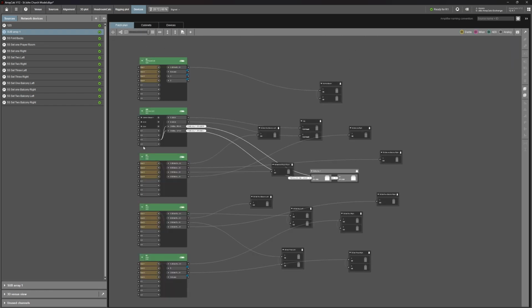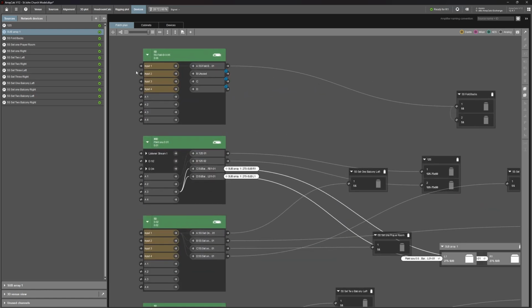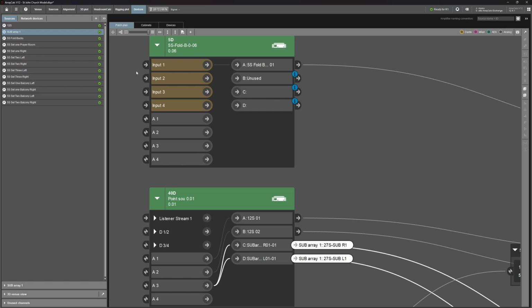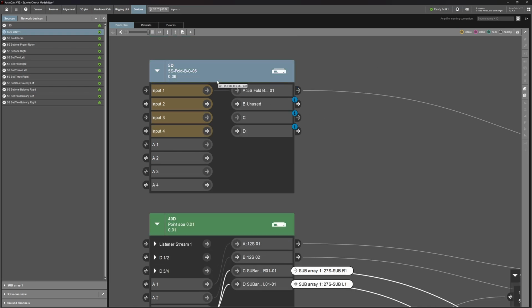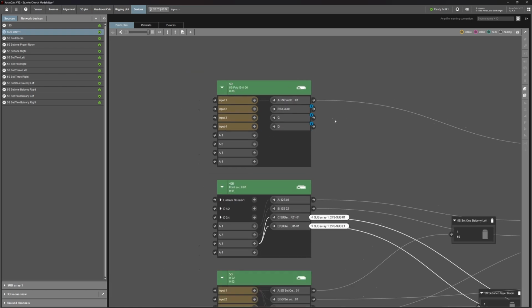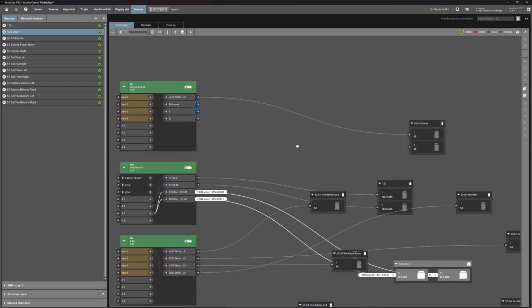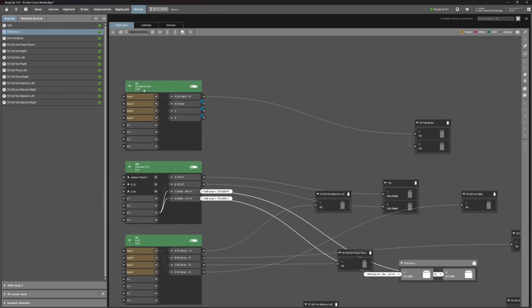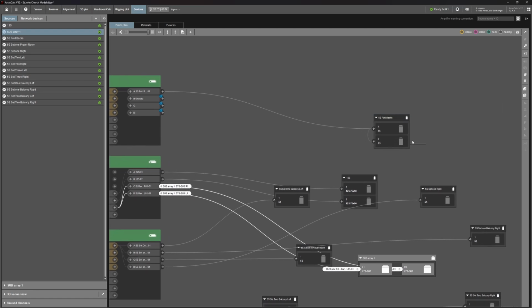So this is the main change, where things like the inputs design is different. And it's really quite nice because you can see the signal path a lot clearer. This 5D is the extra one just because of how the speakers are linked together. So there's only a singular channel, because these are, believe it or not, 4-channel amplifiers, even though they're half a U, which is really quite cool.